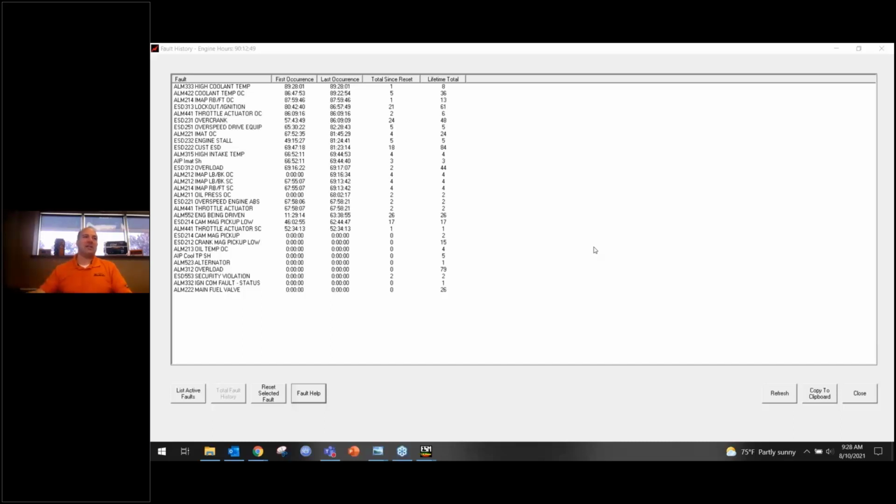When we start seeing that the detonation sensors are going to start coming in and correcting what's going on here, the next piece is I have to delay my timing. I have to go to a safe place where I know I can run, but not where I'm going to risk detonation. And guess what happens to our exhaust temperatures? Yeah, we're not able to use all that power. So we end up where we run into situation number 3.